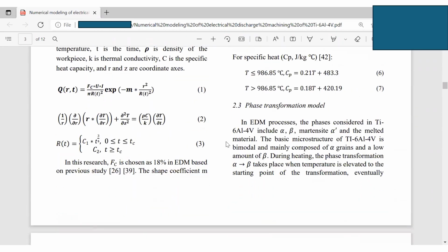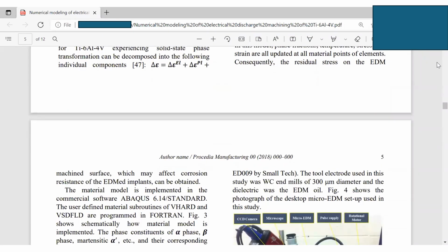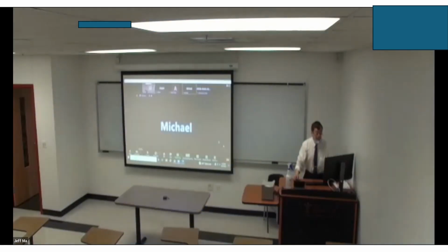Okay, everyone? Any questions so far? And also the methodology you should know. First, when you do the numerical simulation, you must do the convergence test. After the convergence test, you must use the convergent results. You must compare your convergent results with the experimental results to validate your model. The third step is to use the validated model to do the predictive modeling. So these are the three steps, okay? And this one will appear in the final exam. Any questions so far?